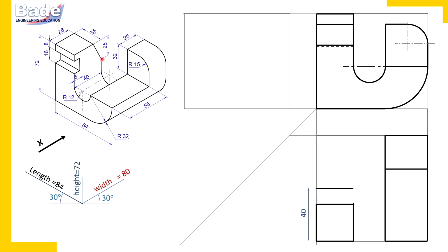Similarly, from this corner there is an edge 28 millimeters long, and these two ends of principal edges are connected by this inclined edge. Similarly, on the other side, that is the hidden side, there is a similar edge, parallel to this edge. So this is how these two parallel edges will appear here. So this is how we have completed this inclined surface which is visible from top.